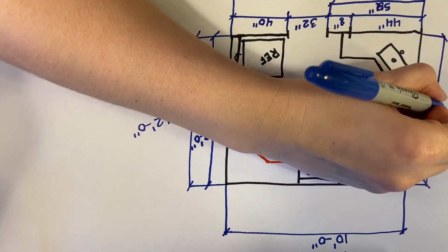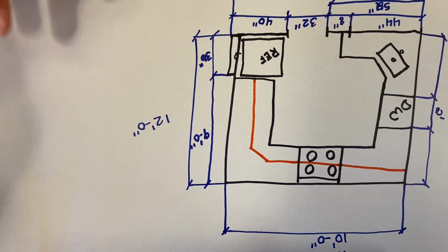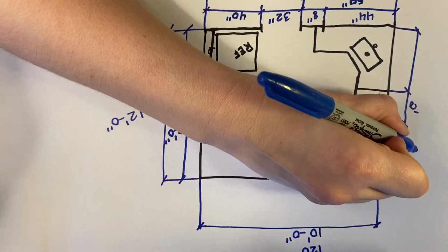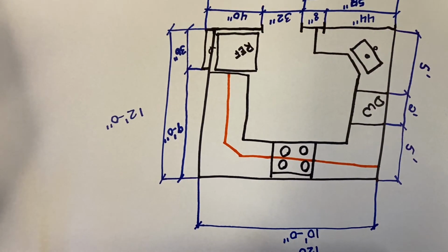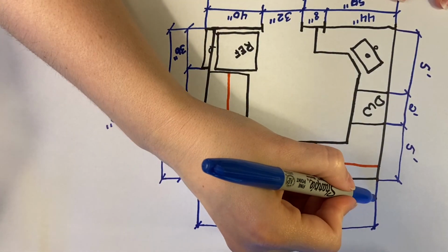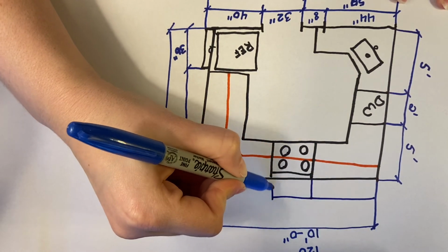So dishwashers are a standard 2 feet, almost always. You might have, you know, a half an inch of wiggle room with your opening, but realistically you're looking at a 2-foot space there. So we are now having a 10-foot space to work with. In this case, it makes our life really easy for planning purposes. And now we've got 5 feet and 5 feet. Very simple, very clean. On this side, we have the same thing. So we've got, there we go.